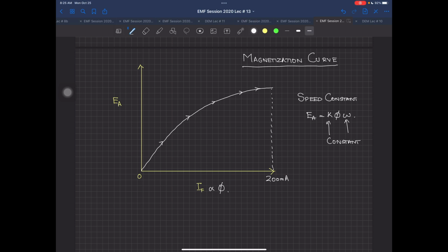Supposedly, during the first half of this experiment, or even in the second half, the light goes off. There is load shedding or something. You cannot continue this experiment. You have to start it from zero back. Now, why is this so? Why have these instructions been given to you in the lab? The only reason is that when you are increasing the current from zero to some value, you are aligning the domains of your ferromagnetic material inside the poles.